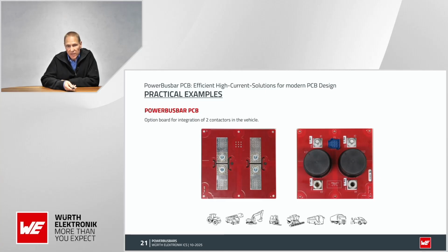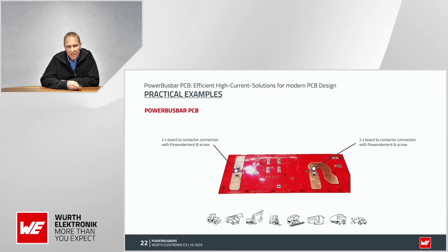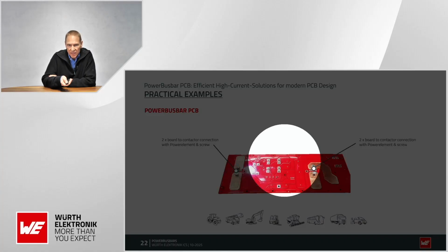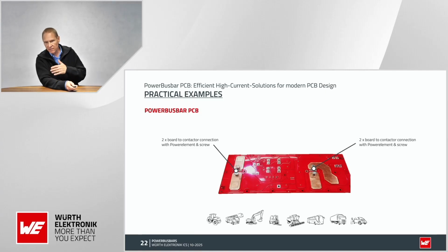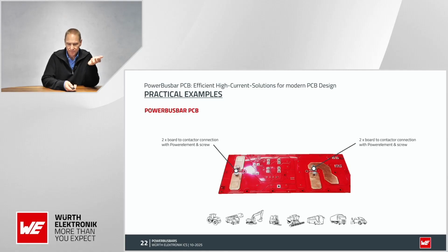And that is good when you use a bus bar in such a system build-up. The next application is nearly the same, a battery disconnect unit. And here the bus bars are a little bit larger, and this also has the advantage that these bus bars dissipate heat out of the system.